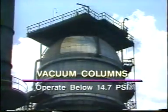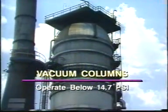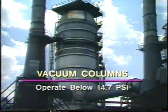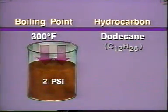And finally, there are columns like this one that operate below atmospheric pressure in a partial vacuum. Towers that operate below atmospheric pressure are called vacuum columns. When we reduce the pressure on a liquid, it boils at a lower temperature. Vacuum columns reduce the amount of heat that is needed to vaporize hydrocarbons because they operate at very low pressures.